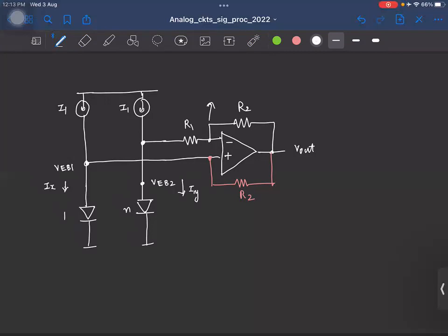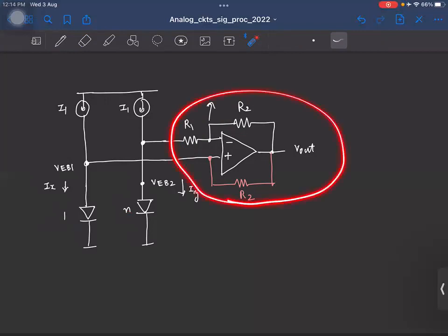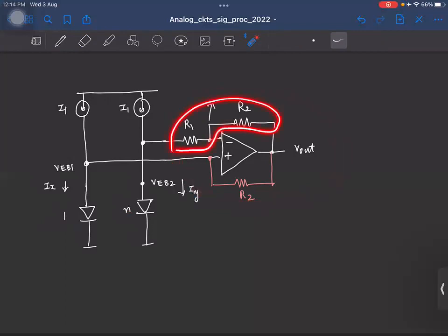Why is R1 redundant? Remember, why was this R1 and R2 in the circuit in the first place? We needed the gain, right? See, we need these two diodes for sure. That was the whole point. That's where we started with. We need this fellow also, right? Because this is what is giving you the required gain, and this is required to add the current.